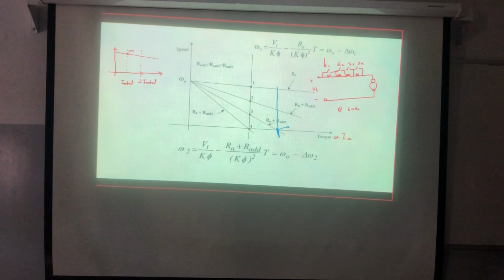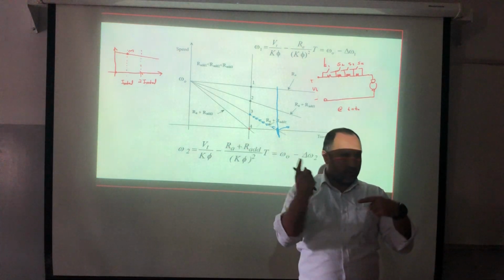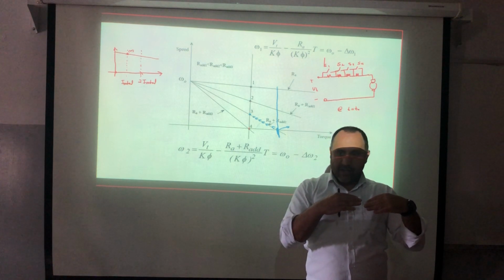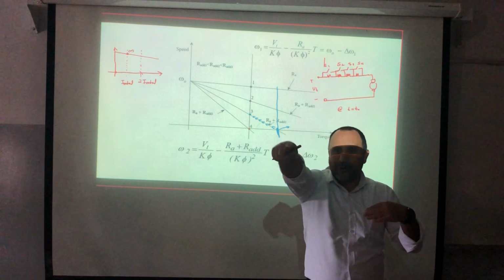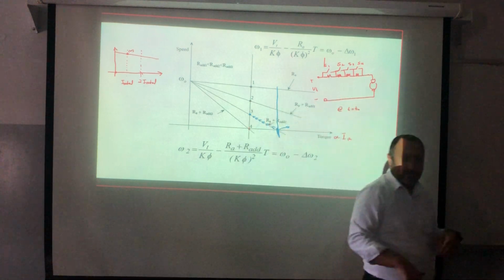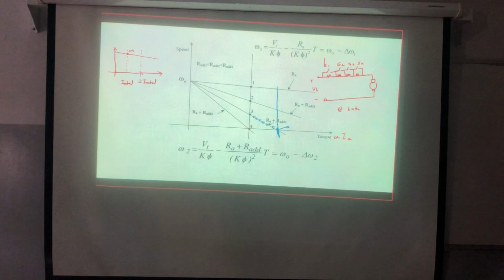You know that the machine will try to accelerate. Following what? The second line, let's say, a torque speed characteristic, until I'm reaching where? 1.3. Now the current is what? Equal the rated. I should switch now. By switching, this means what I will do? Change the armature. I will reduce what? So one of the switches will be closed, correct? Increasing speed. Let's assume that this switch is closed.